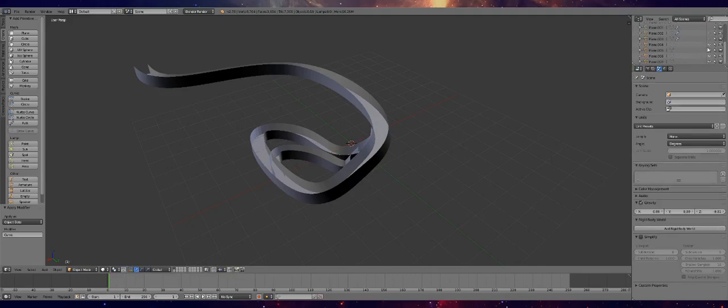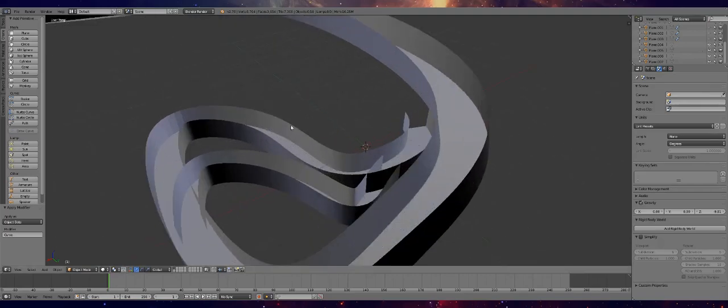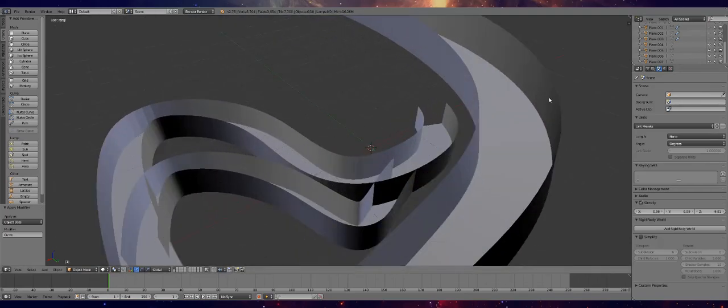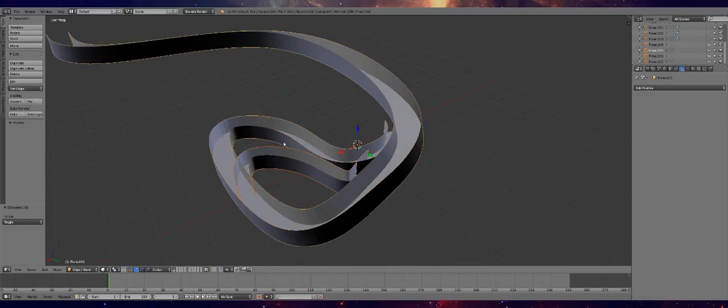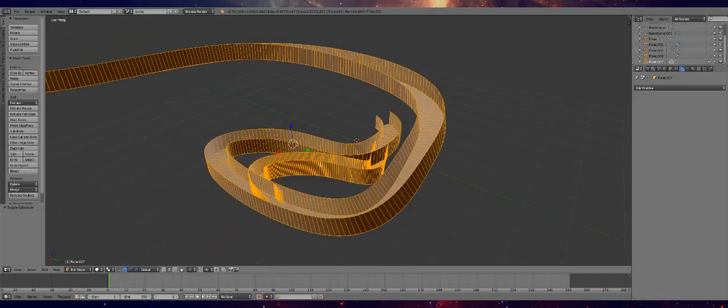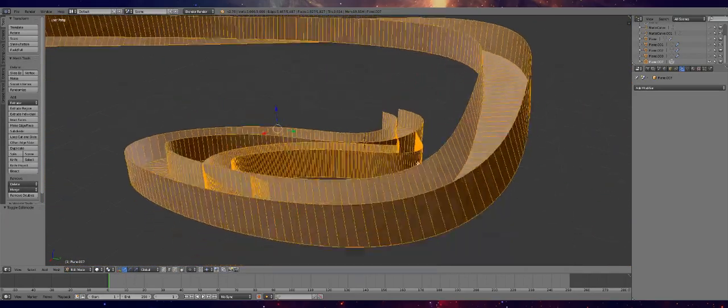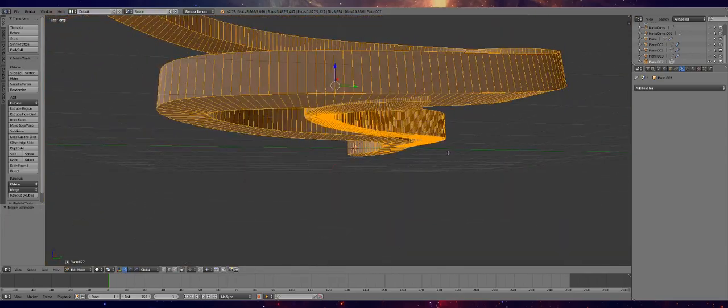I would go ahead and hide everything you don't need, and now we have pure objects that are just our new track. What you want to do is select all of those objects and click tools, and sorry, I'm gonna go into select one, select another, join, then select another one, join, and keep doing that. You have to join 2 by 2, but hey, that's the way. So when you edit, you will see that now all those objects are one single thing.